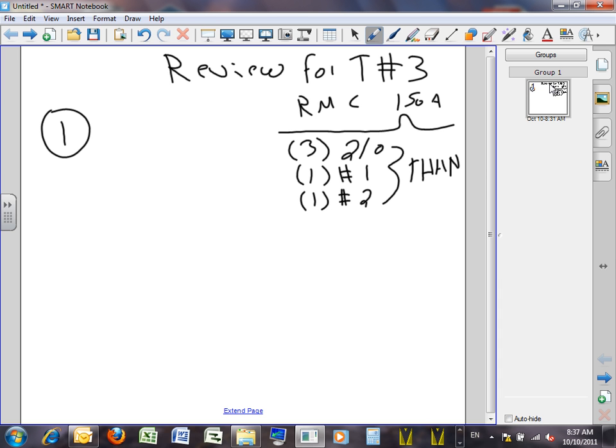The question would be, could you please size a conduit that can carry these conductors. A feeder has these conductors, 3-phase conductors, plus neutral, plus ground, and we need to size a conduit that fits. And the conduit type is rigid, right? Rigid metal conduit.